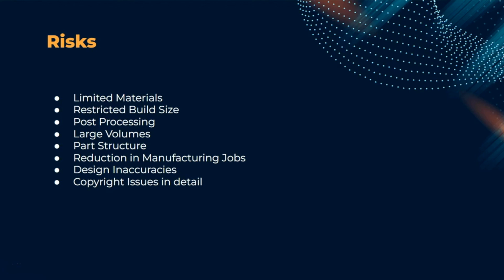Additionally, the actual printing of the design is done layer by layer. While this process ensures the product is cohesively joined together, it also presents the risk that the product can be divided into layers if the materials are under stress due to misconfiguration in the design settings.